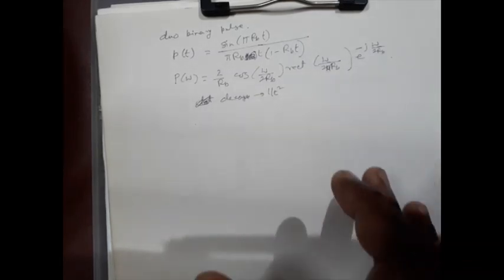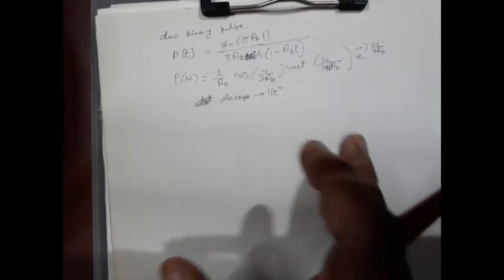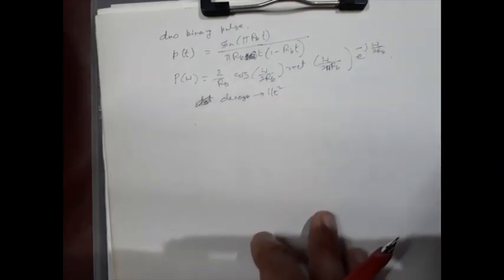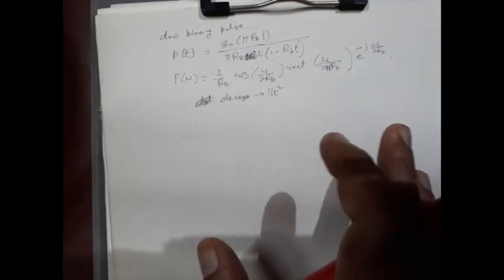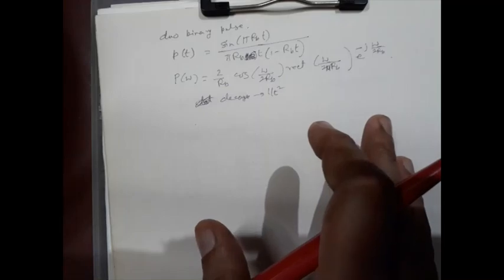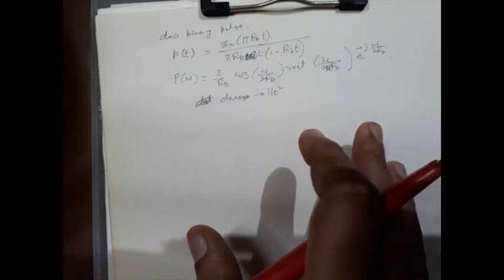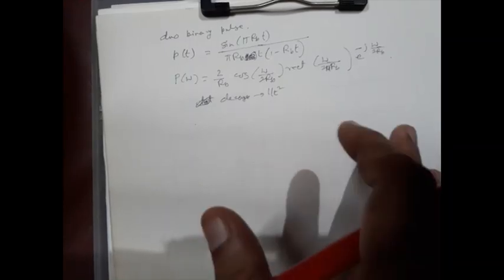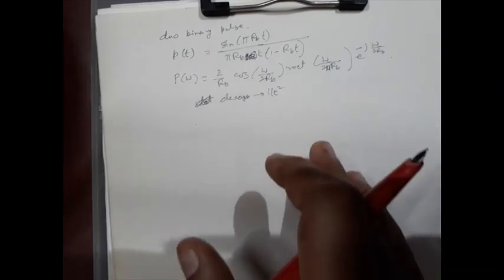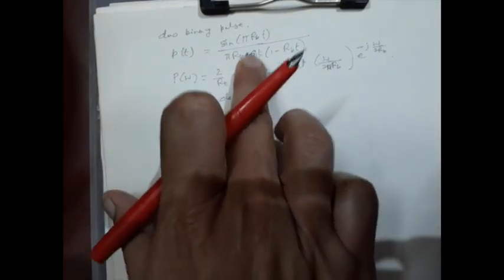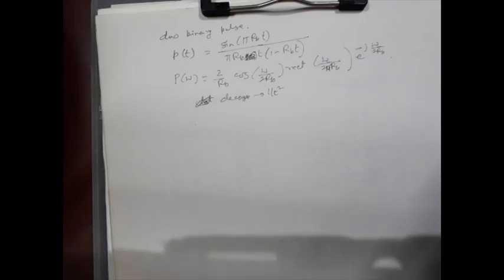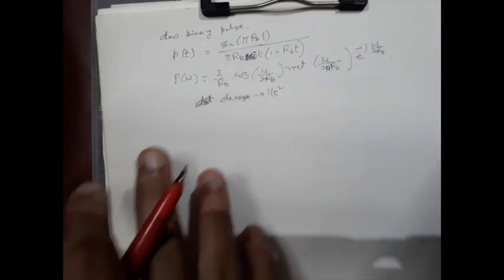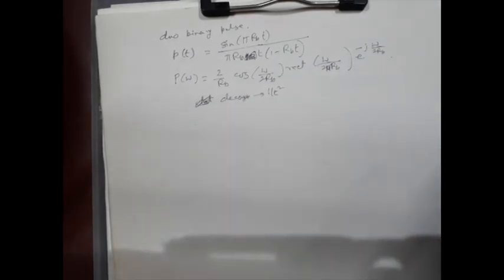Now the raised cosine pulse satisfies the criteria for the partial response. So the data transmitted by the raised cosine pulse can be detected using Nyquist criteria for 0 ISI or using the controlled ISI method. The problem is that it requires twice the bandwidth of this pulse. So this is what we have to say about intersymbol interference.